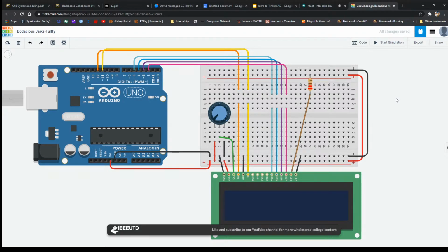So essentially when you want to either move the cursor or clear the display, all these instructions would be done in instruction mode. Now the other mode is character mode, which is when you actually want to display characters or print output to the LCD. So there's 2 different modes.